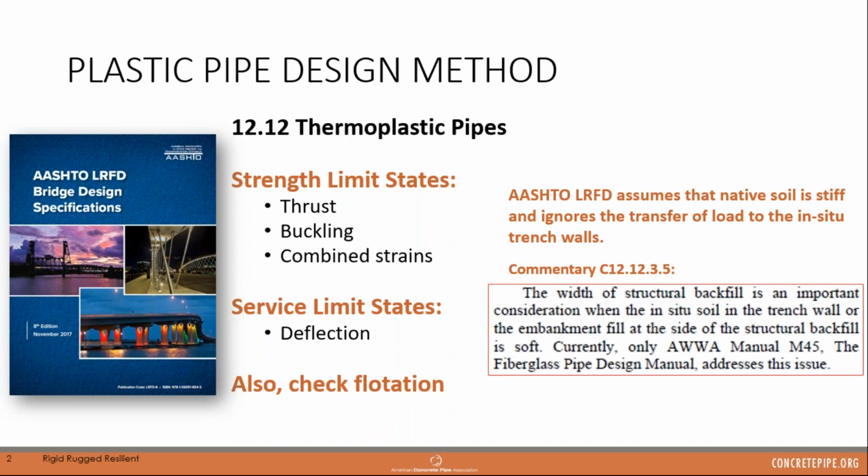So yeah, the basic design principle being that if the native soil is really weak, you need to remove more of it and replace it with a stiffer backfill in order for that plastic pipe to be able to deflect, to transfer the loads into the soil.